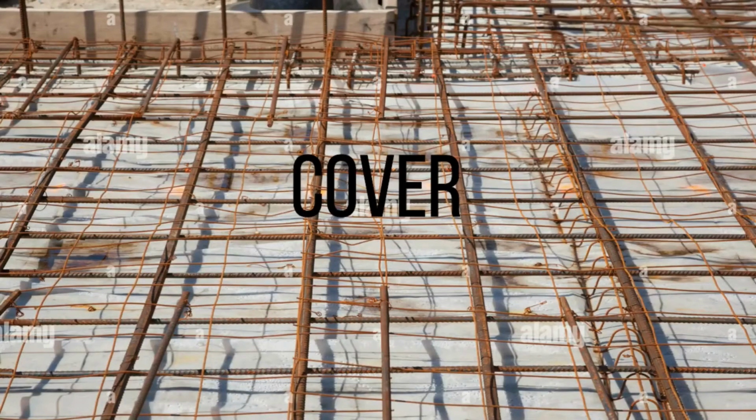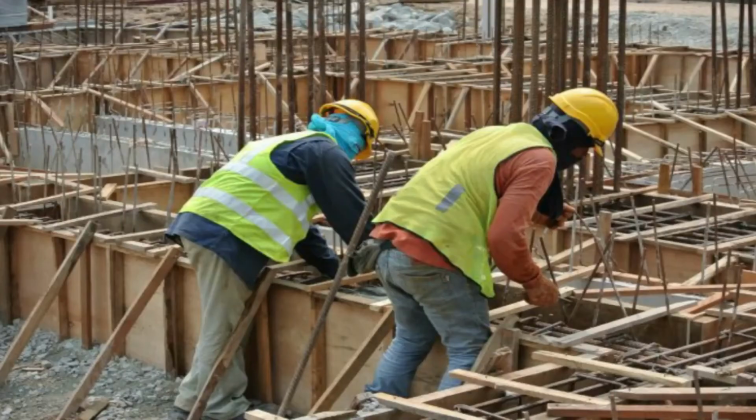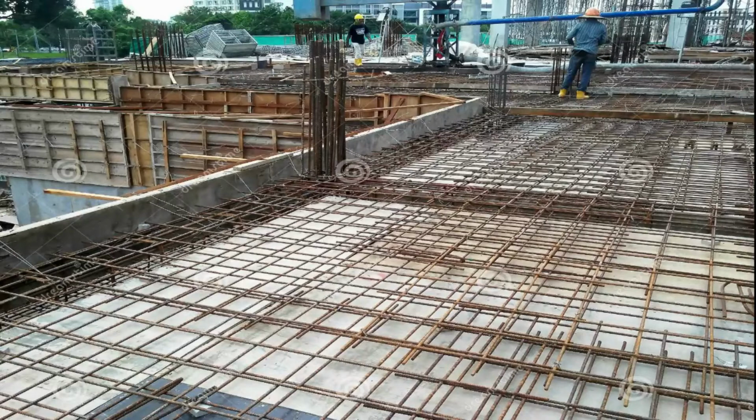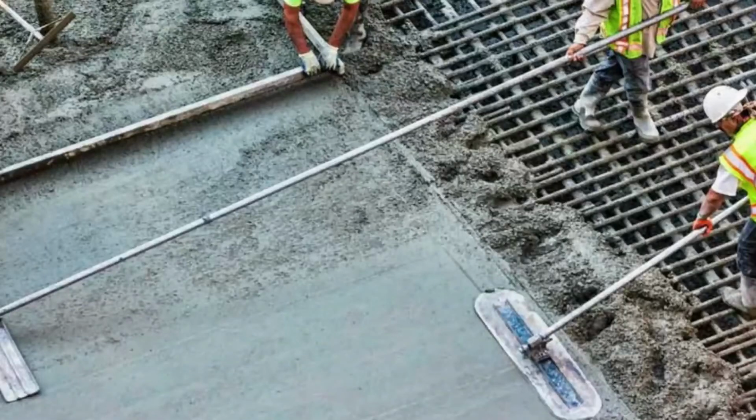Cover. One important reason for placing the reinforcing steel properly is to achieve the right amount of concrete cover, the amount of concrete between the reinforcing steel and the surface of the concrete member. Cover is the single most important factor in protecting reinforcing steel from corrosion. Cover is also necessary to assure that the steel bonds to the concrete well enough to develop its strength. The requirements for minimum cover are usually listed in the project specifications or shown on the drawings. Where not specified, the minimum cover for cast-in-place concrete is specified by the ACI 318 Building Code.